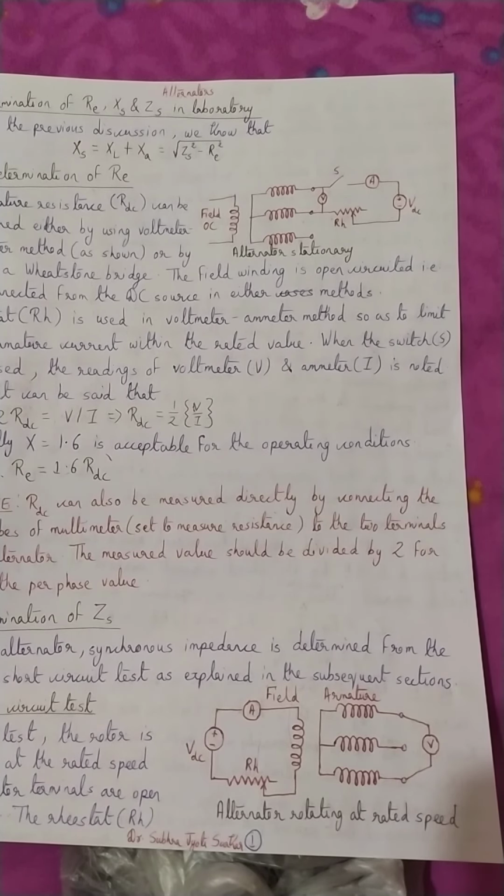So we would be putting it in the table. Now, once we are getting a value more than the rated value, and we could see that the value of V is not varying significantly with the variation of I, that is, V has become more or less flattened in nature, we would be stopping at that particular point. We would not be moving further.